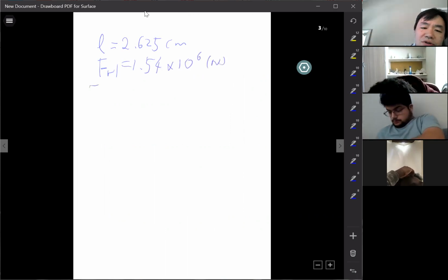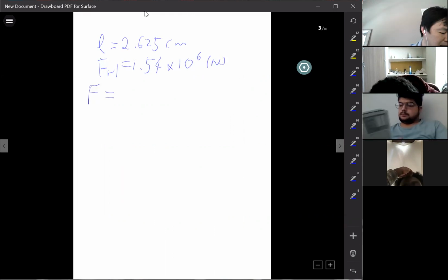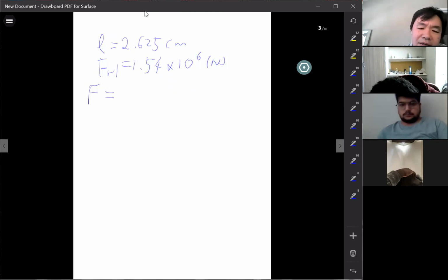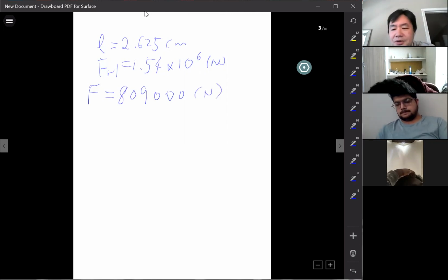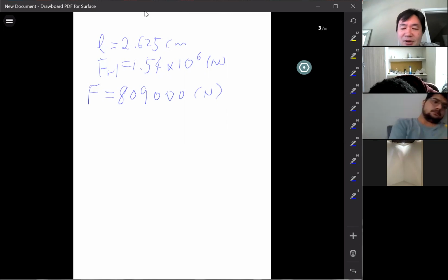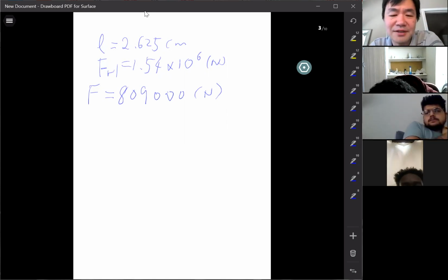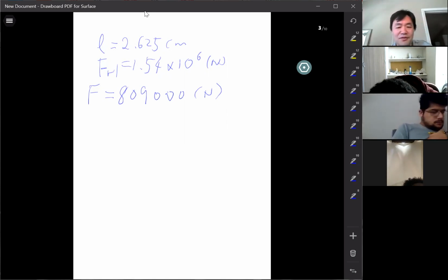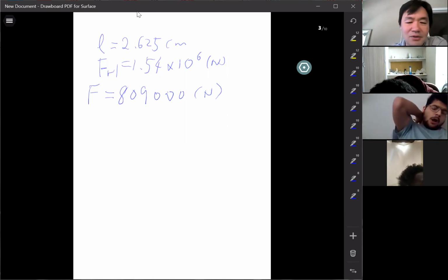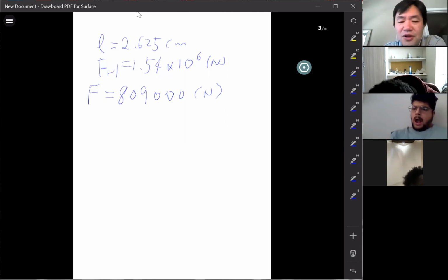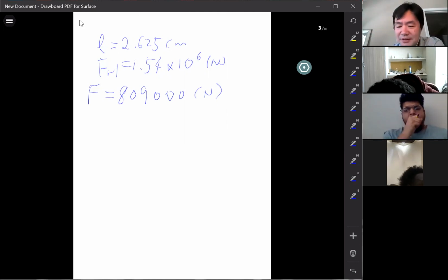So my F value calculated is 800,000 something. Let me see. 809 kilonewtons. Yeah, 809,000. I don't like kilonewton because directly from your calculation it is Newton. Kilonewton is a conversion, right? So the number you key in your calculator will be 809,000. The result from the number you key in your calculator will be like this. So this is the force required to open this gate. Okay.